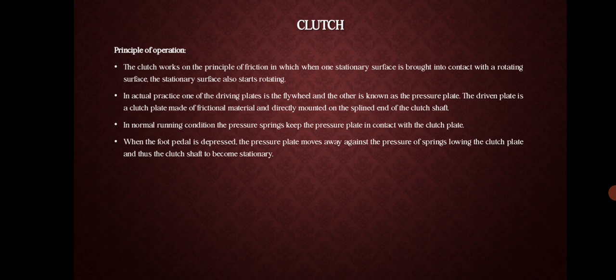In normal running condition, the pressure springs keep the pressure plate in contact with the clutch plate. When the foot pedal is depressed, the pressure plate moves away against the pressure of the springs, releasing the clutch plate and thus causing the clutch shaft to become stationary.